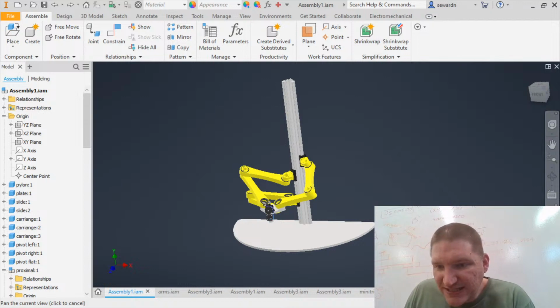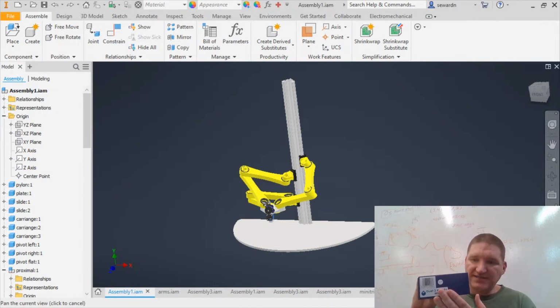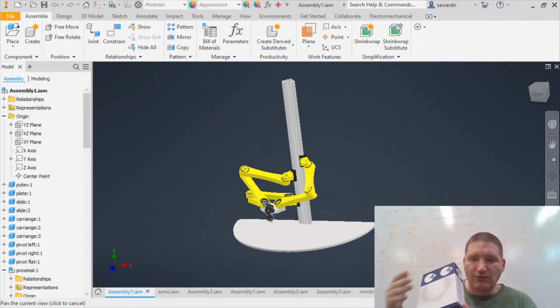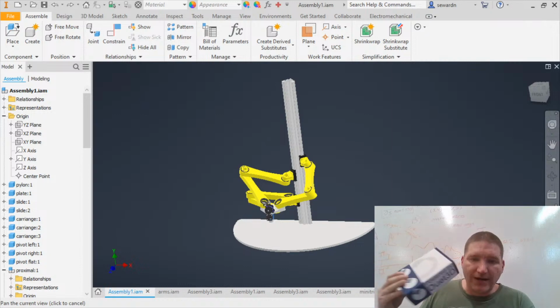All right, are there plans for the machine? Let's see, Radish Dalek: are there plans for the machine to have positional feedback? I imagine a single magnetic strip shared by each sensor, one sensor per carriage. Yeah, feedback would be great, so you can know if you miss steps. I'm going to use this controller here, and it will actually know if it misses steps, so I can know if I ever lose position. I'll just tell it where to go, and the steppers will go there. If it can't handle it, it'll miss, and then I can take action. So any kind of feedback on the carriages won't really give me any more than what I already have.